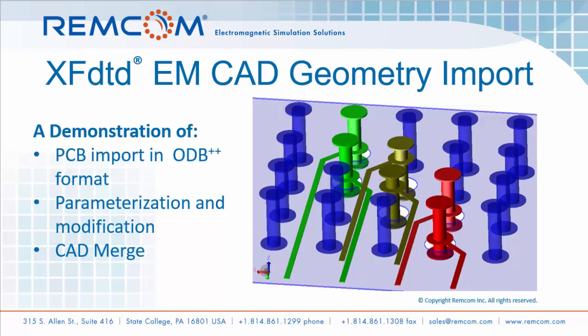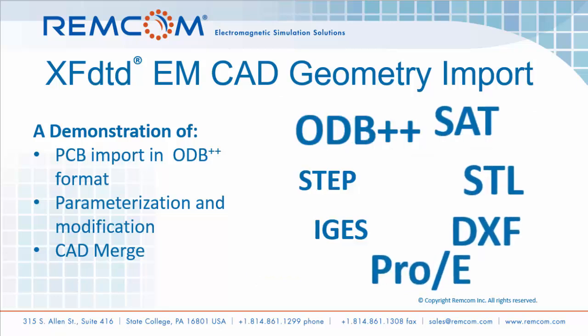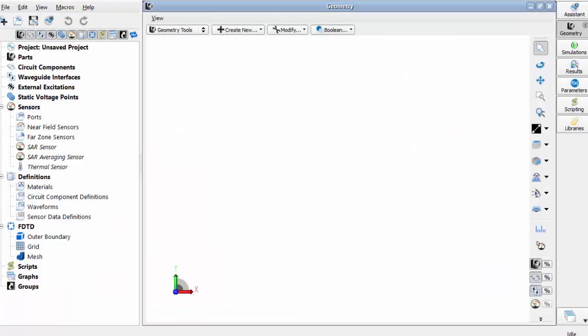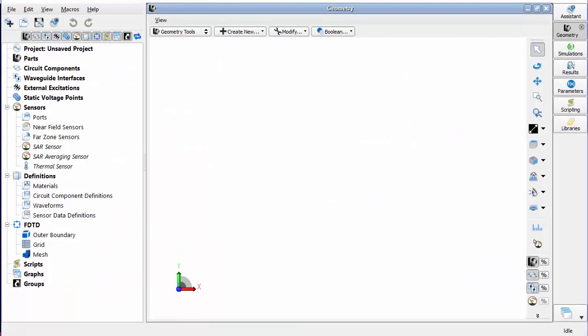Welcome. Remcom's XFdtd fully arbitrary 3D electromagnetic simulator includes the capability to import CAD geometries in many popular formats. File formats available for XF include ODB++, SAT, DXF, and STEP. Let's start with an import of a PCB in ODB++.